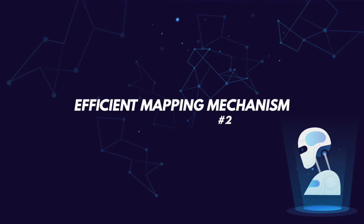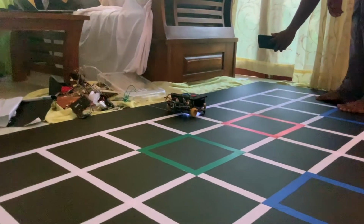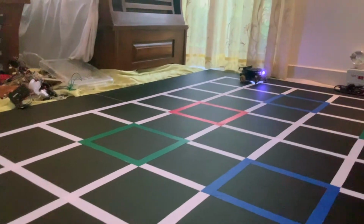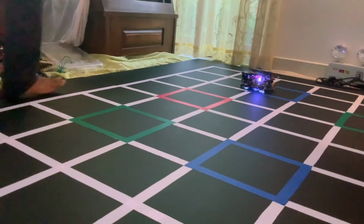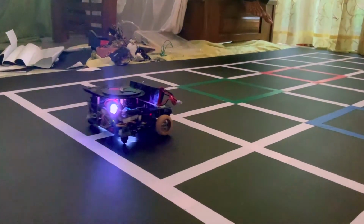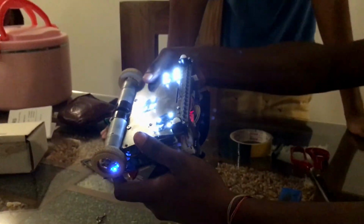Efficient mapping mechanism using 3 color sensors. As you can see in the video, our robot does not go through each and every path of the maze. It goes along one line, skips the next line, and directly goes to the path next to the skipped path. This is possible because we have used 3 color sensors to detect the paths in the maze.